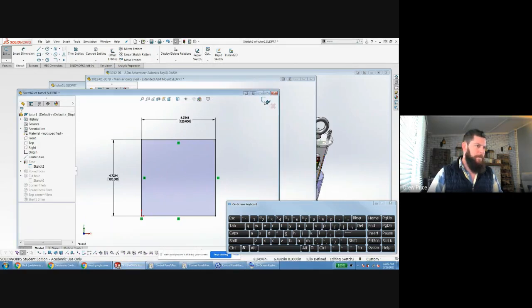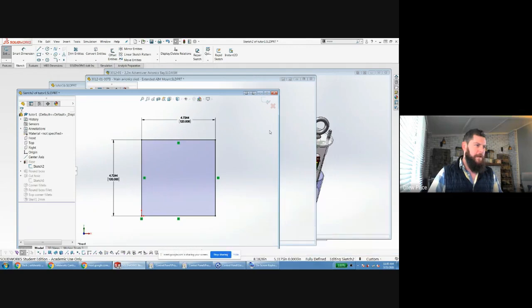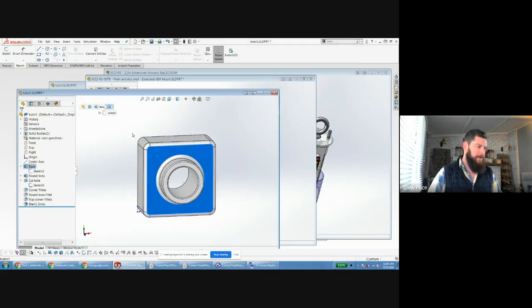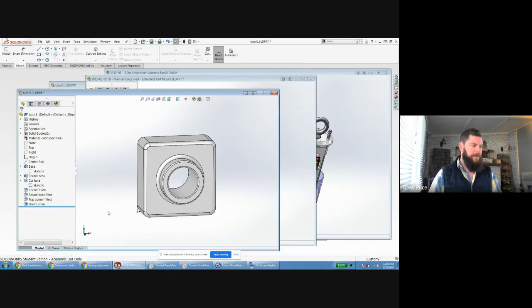There is one behavior that you might find yourself stuck in where, for example, you were trying to create a sketch on a particular face or plane or something like that, and you find that if you go and click on it, you can't actually select what you wanted. If you look at the bottom here, I've got this bar open of filters. And to get the filters bar open and close, you push F5 on the keyboard. You can also go up into tools and turn on the filters bar. So the filters bar will let you do things like only select faces or edges or reference geometry so that you can quickly come into a model and select only particular features that you want.